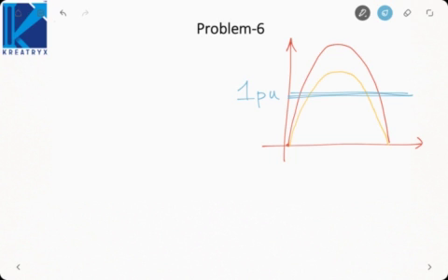Now, earlier when the oscillations were going on, they were going on up to 130 degrees. We know the system will lose synchronism if we go beyond this point. So this point must correspond to 130 because this is the maximum point in the rotor oscillations. So this will form the critical case. Let me call it delta X. Now if delta X is equal to 130, this will be my critical case.